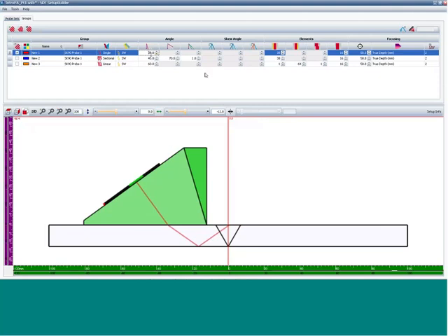Okay, this one A-scan starts on element number 30 right here, and uses 16 total elements. So 16 elements times the pitch of each element, 0.6, equals 9.6 millimeters. So my aperture here is basically a 10 millimeter probe.